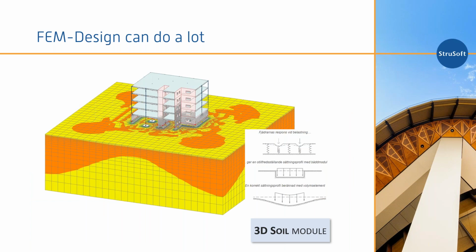A very powerful module is the 3D soil module, which handles soil as 3D finite elements. You can get a very realistic interaction between the soil, foundation, and superstructure, and analyze it as a whole, as one big model.